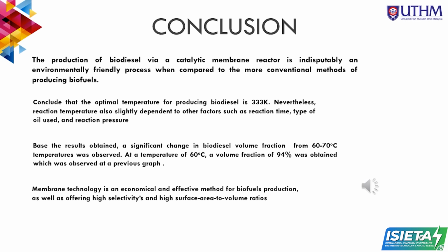Catalytic membrane reactors allow for simultaneous reactions and separations, leading to higher reaction rates and increased product purity. Additionally, the use of a membrane in the reactor allows for continuous operation and can reduce the need for downstream separation processes. This research found that the optimal temperature for producing biodiesel is 333 Kelvin.